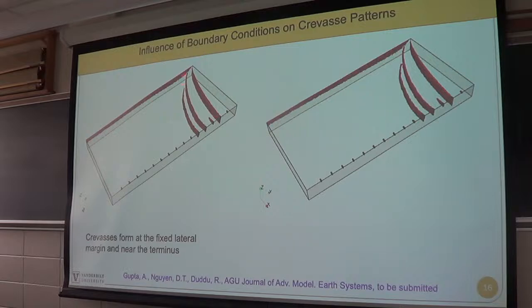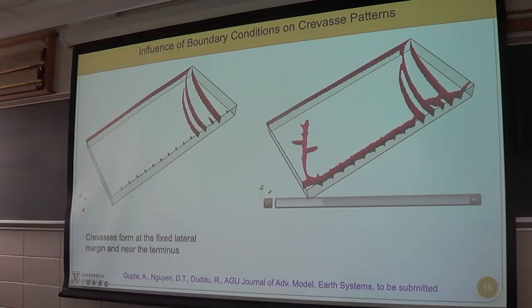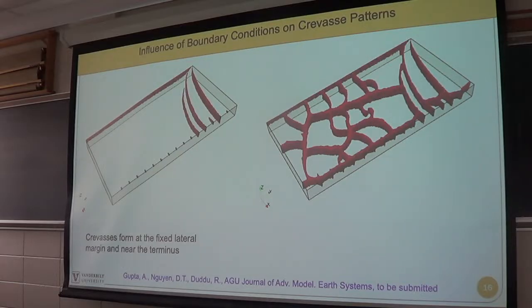And then we said, what if for some reason this fixed boundary became free slip? Maybe the fractures went full depth and the glacier slid. So what happens then, given this as the initial condition? Remember, our idea was a unified fracture framework, where we capture not only the flow deformation of ice, but also some kind of initial damage state effects. So I take this simulation endpoint and change the back face to free slip, and then I look at it, and I get these polygonal fracture patterns that just rip through the rest of the domain, right?